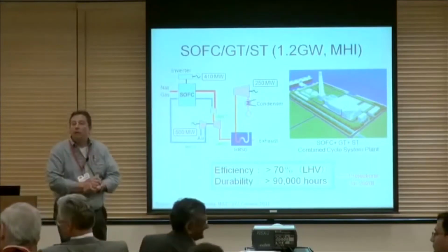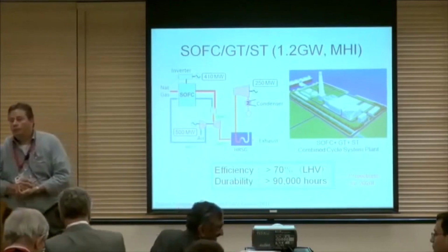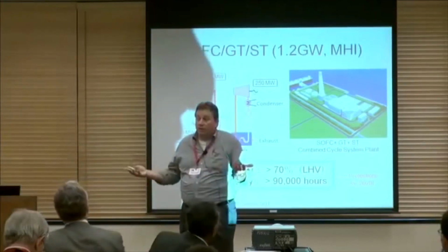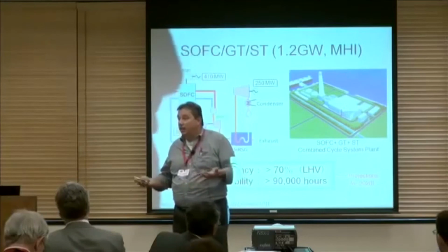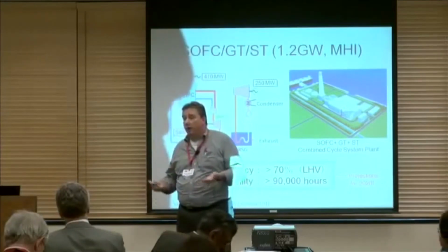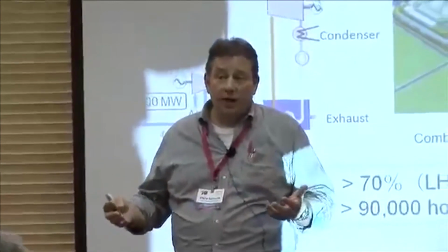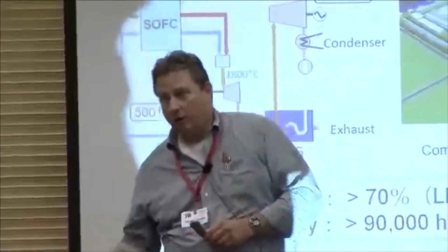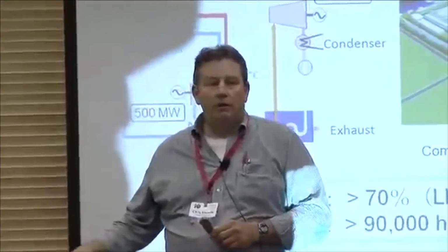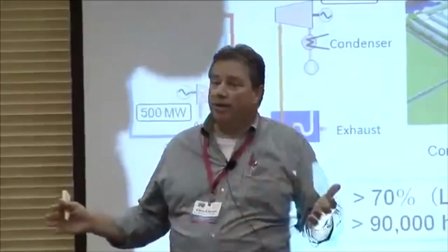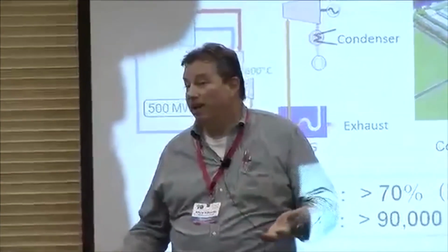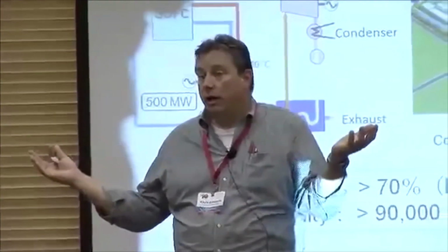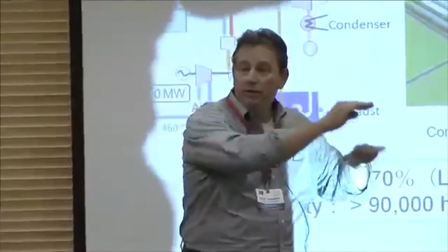Okay, yes, sir. How much is second law efficiency actually used in practice to evaluate alternatives? So when you talk about compressors and turbines, adiabatic efficiency, isentropic efficiency is second law efficiency. It's our mainstay for how we evaluate those things. When you talk about bigger systems, you've got to pick an architecture, right? A turbine is really simple. Same inlet state, same outlet pressure. That's an HS diagram from it. So it's a simple system. When you get to a more complex system, you've got to agree upon a system, and it has to have a reversible limit. It becomes a lot less useful to you. But exergy efficiency, you can still do it, because it's about the resource and how you manipulated the resource going through.